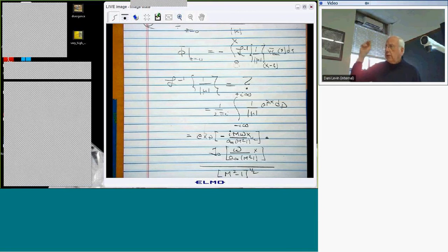And you might think, well, why do you want to know that? Well, first of all, it's fun to find it. But the other thing is that people do something called aeroacoustics, where they're interested in high-frequency oscillations of surfaces that give rise to far-field noise. For example, you might have a panel that's responding to a turbulent boundary layer, and they use potential flow theory. They use a combination of things. They do a local solution near the body.